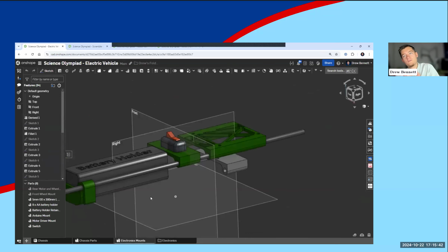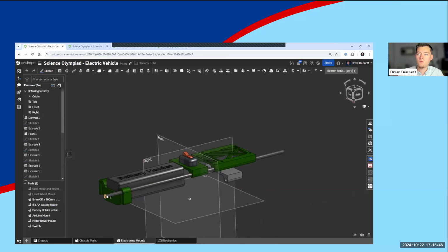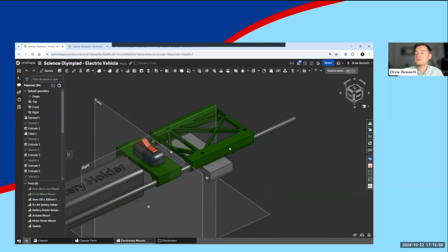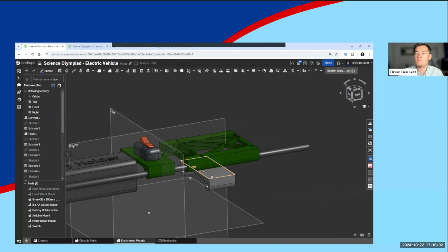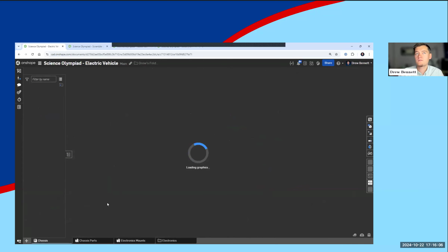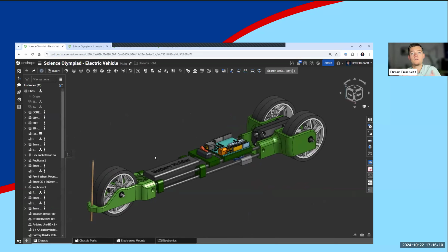I actually wanted to design the electronics mounts in a separate modeling environment. So I brought over the important parts, AKA that 5mm carbon fiber rod that's going to act as the chassis spanner across the middle. And then I modeled up my battery holder, my switch that I can poke with a number 2 pencil, and the other mounts for my Arduino board, as well as the motor controller that's going to sit right below it.